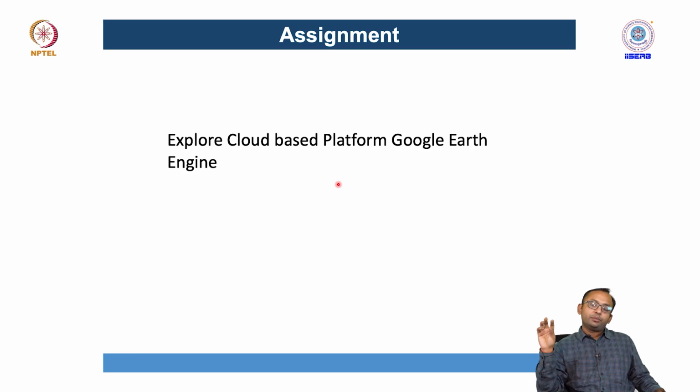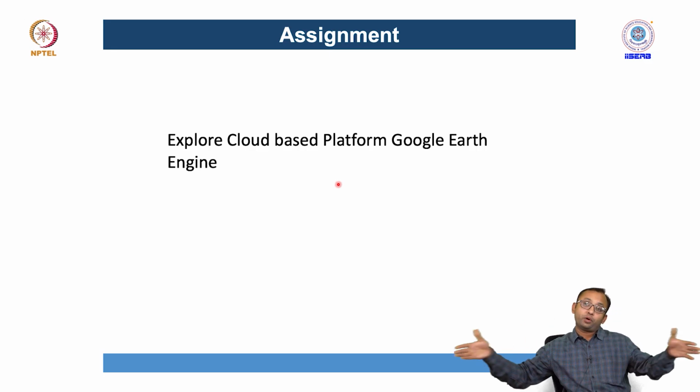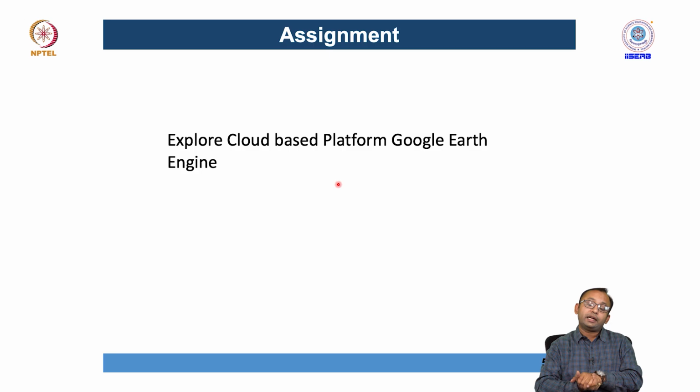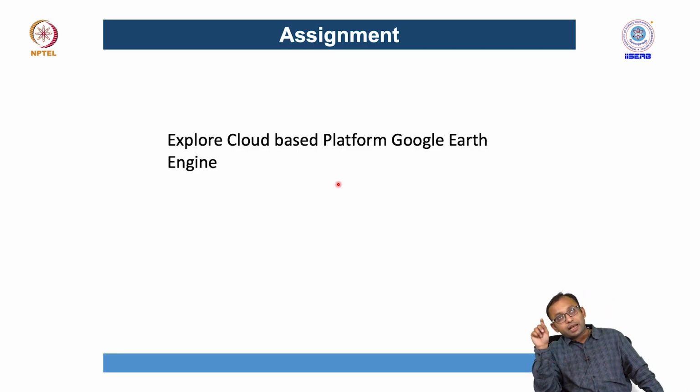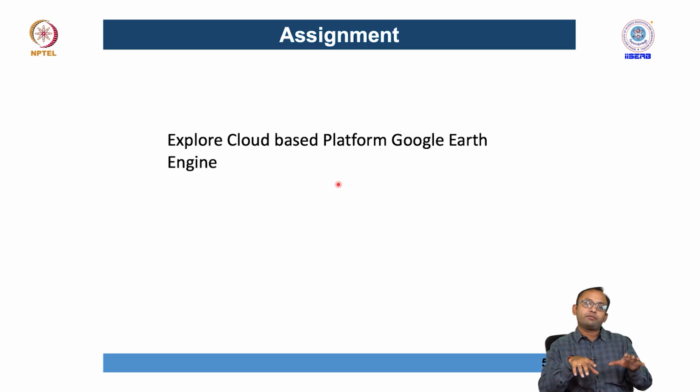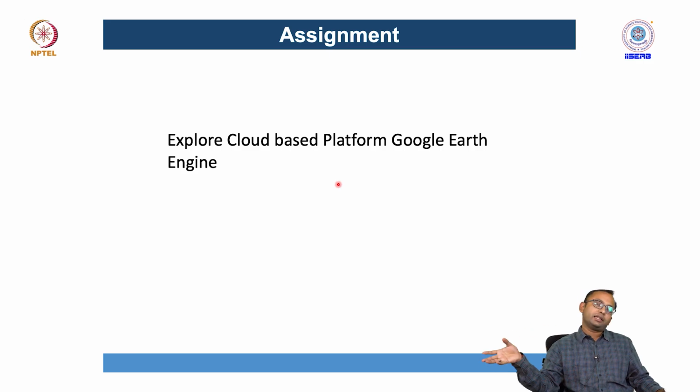Once that is done, you look at different indexes that tell you which area is water area and which area is non-water area. Then you can do multiple temporal analyses and aggregate them together, and tell which pixel has more frequency of water, which has more frequency of non-water, or which has a mixed frequency. Based on this, you can calculate the frequency and probability of occurrence of water pixels in different areas. Wherever you have higher probability, it is likely that water will always come there.